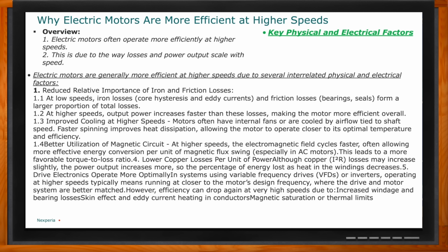Improved cooling with speed. There are usually 2 internal fans, one right by the shaft on the output and one where the actual wires go in. As the motor spins faster, the fans built into the shaft also spin faster, so that gives you better cooling, with the airflow going through. So higher speed, more airflow, better heat dissipation. The motor will stay near optimal temperature, so much better performance.